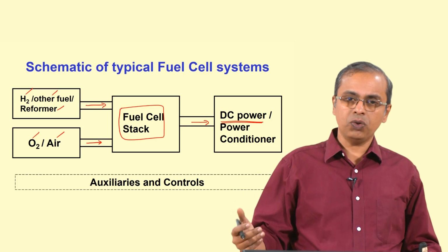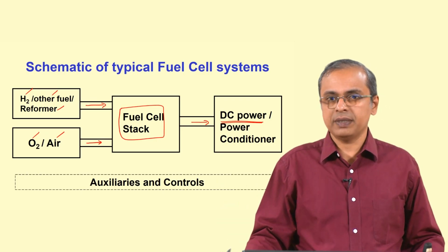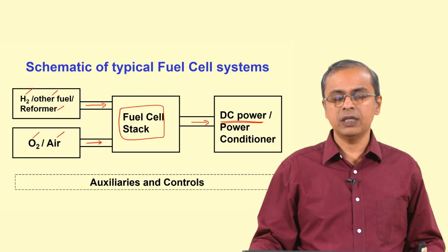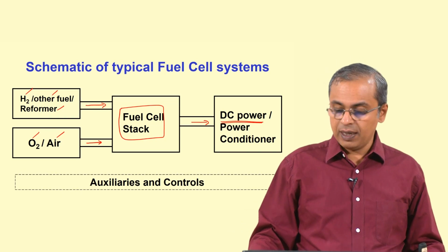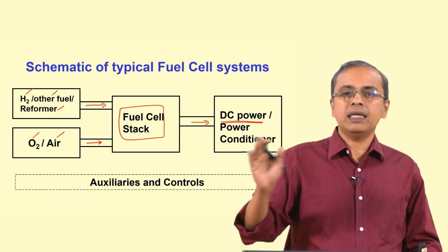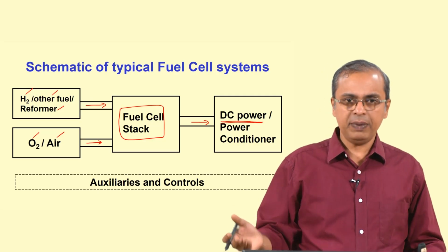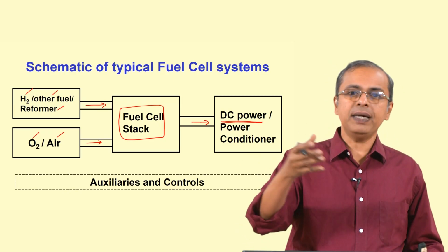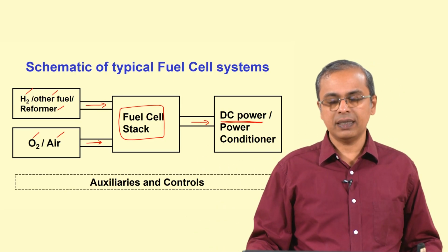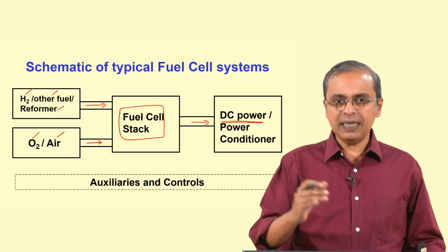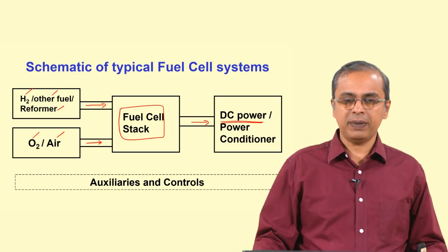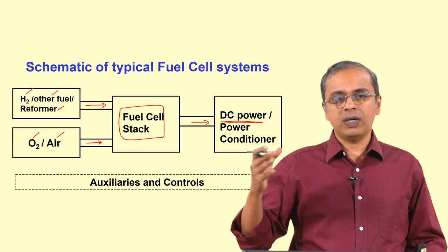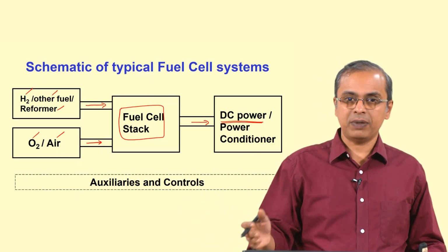And then when it comes closer to home, you just drop the voltage to something that is acceptable. Internationally it is typically somewhere between 110 volts and 220 volts, and then that is sent into your household appliances. So, often DC power is not directly being used in the household, or in many other places. So, the output from the fuel cell is often not directly usable. You can make it directly usable if you accordingly design the appliances that run off of a fuel cell. But generally speaking, if some fuel cell supplier would like to supply a system that works in your household, they would need to set it up such that your existing appliances will work with the fuel cell system that they are supplying.